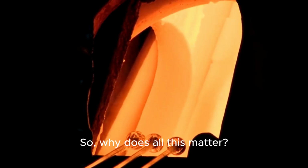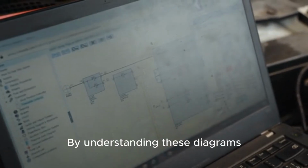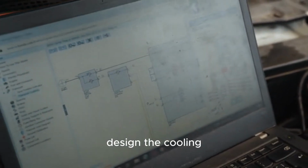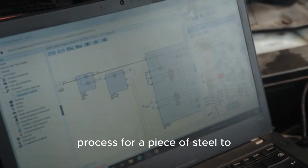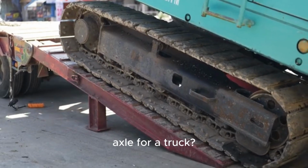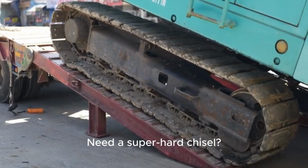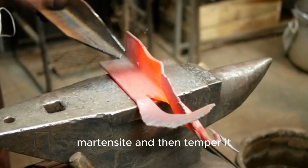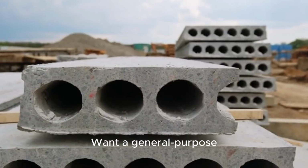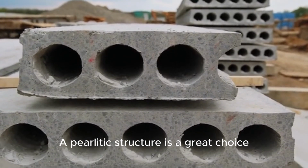So why does all this matter? It's the core of heat treatment. By understanding these diagrams, engineers can precisely design the cooling process for a piece of steel to achieve a specific set of properties. Do you need a tough and durable axle for a truck? You might aim for a bainite structure. Need a super hard chisel? You'll quench to form martensite and then temper it. Want a general-purpose steel with a good balance of properties? A pearlite structure is a great choice.